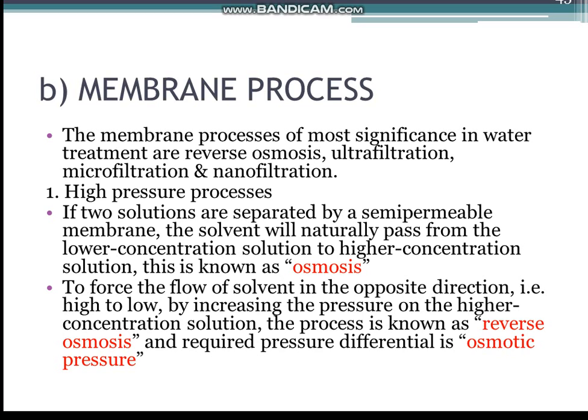Next, membrane processes. The membrane processes of most significance in water treatment are reverse osmosis, ultrafiltration, microfiltration and nanofiltration. These processes have traditionally been applied to the production of water for industrial or pharmaceutical applications, but are now being applied to the treatment of drinking water.